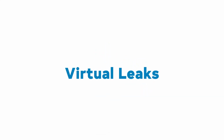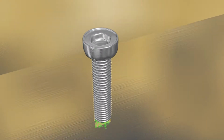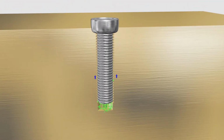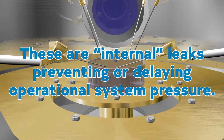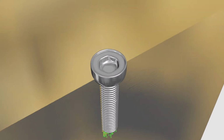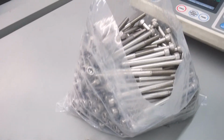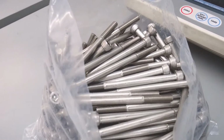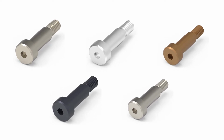4. Virtual leaks. A virtual leak is a trapped volume of gas at the base of blind tapped holes within a vacuum chamber that cannot be easily pumped away. These are internal leaks, preventing or delaying operational system pressure. Fasteners are typically the source of virtual leaks in sealed systems, as there may be voids between the parts being restrained, the threads and shoulder of the screws, or other incompletely filled holes.